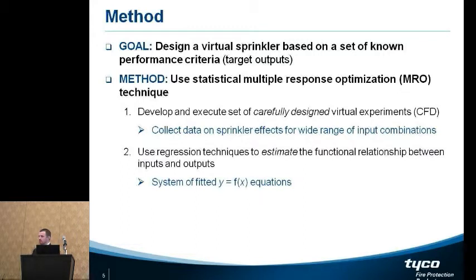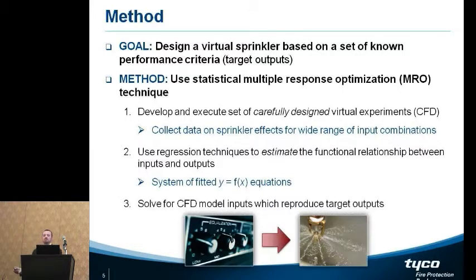And then we're going to use regression techniques to estimate the functional relationships between those inputs in the model and those target outputs you've gotten from some test data, to create a system of fitted y equals f of x equations. And then we're going to solve those simultaneously, essentially, to derive the inputs we'll need for the model, and in so doing, calibrate the spray for this particular application.